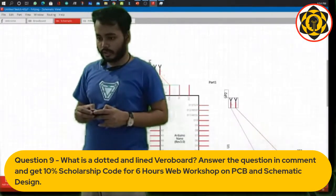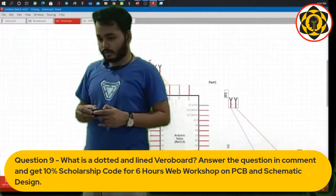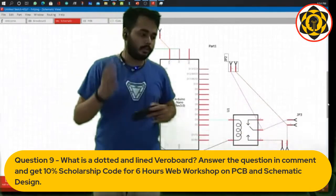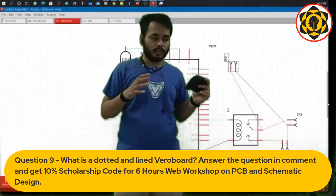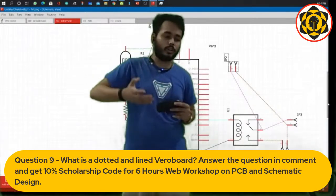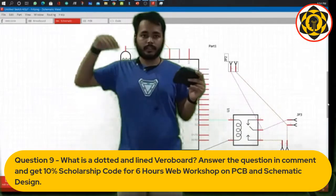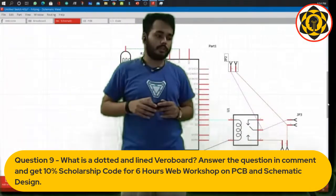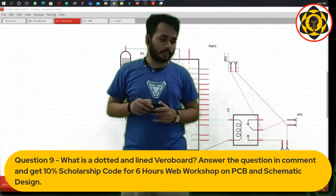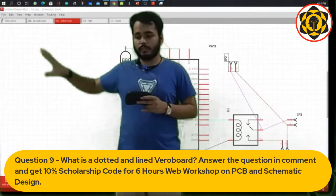So this is our low voltage side. So this is where the converter will connect to the external circuit. It will connect here. So this is the area. This is the low voltage side, and this is the high voltage side. This is also done basically because if you keep the high voltage and low voltage side together, the microcontroller works on a clock, right? Clock frequency, and then the high voltage side is alternating, so that interferes with the clock frequency. So to prevent that, we usually do this trick where we sort out the stuff into a high voltage and a low voltage side.